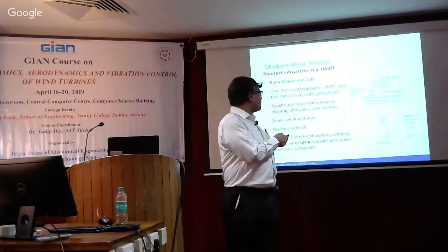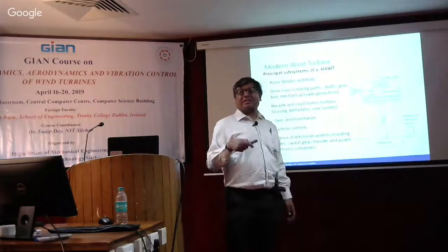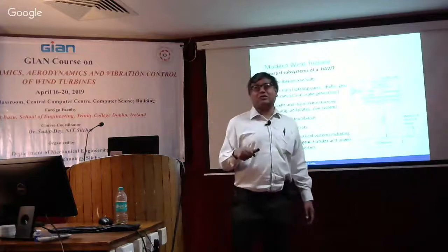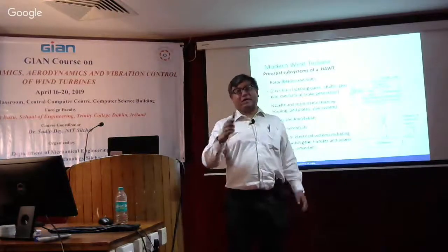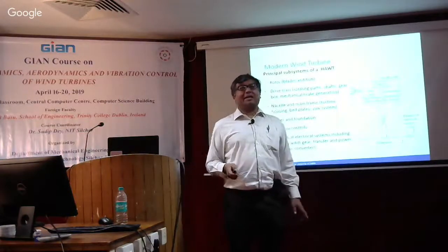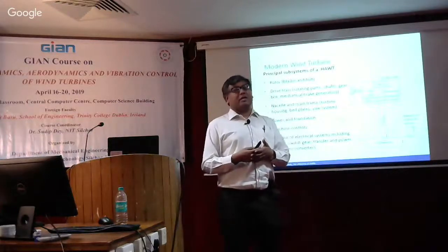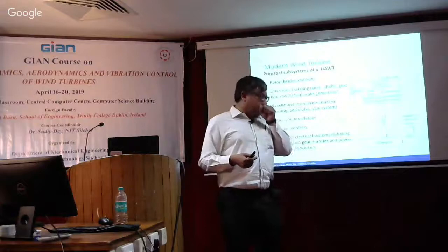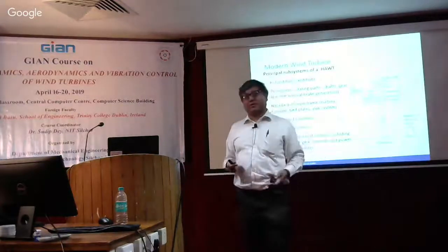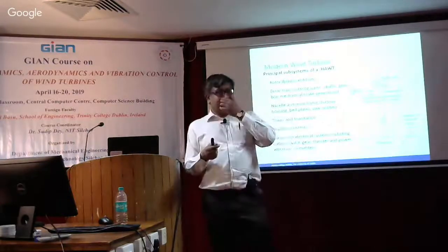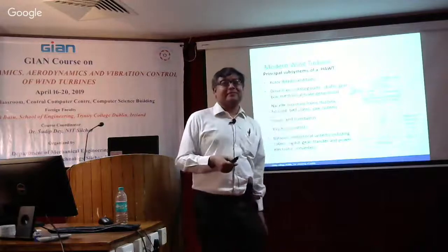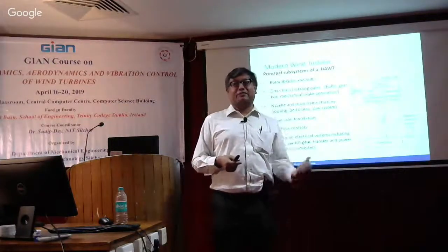Damage in a gearbox is more frequent, but the effect is not that significant. So obviously, we need to look at both, but in different ways. A regular condition monitoring of the gearbox would tell you when you need to order the next gearbox, because you don't want to wait until the gearbox gets fully damaged.